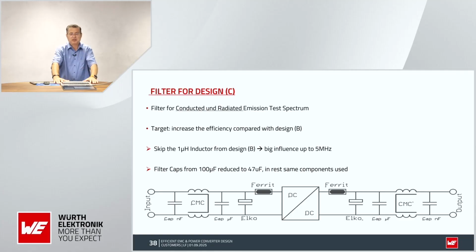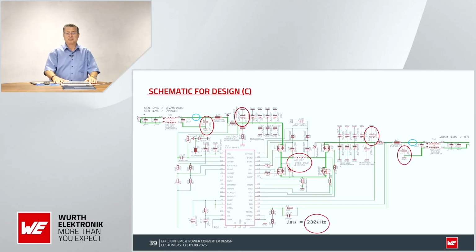For the input filter, I will skip the inductor. I will leave just the ferrite bead. Same for the output. I don't need it because my frequency is too slow. I'm not afraid of that. And that's my final decision.